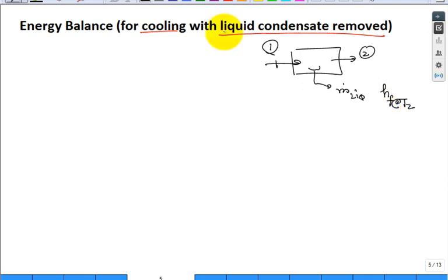All right. Now, the way it worked was you had a cold refrigerant coil there. Either what they call a DX coil, because it's direct expansion, inside the tubes is a refrigerant that's evaporating, common, or even just as common in big commercial applications, it's water, cold water, chilled water inside the tubes.